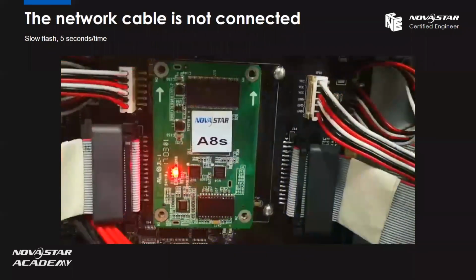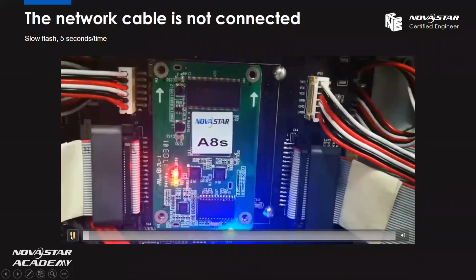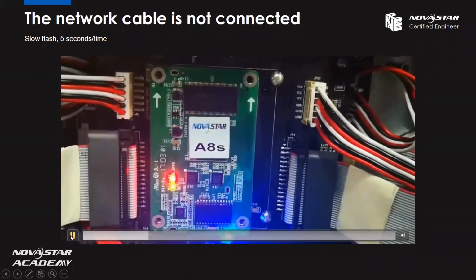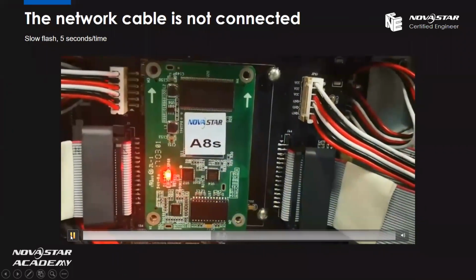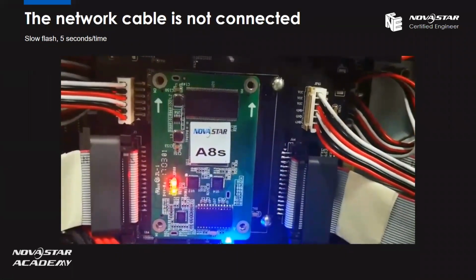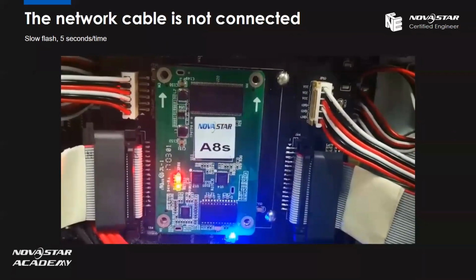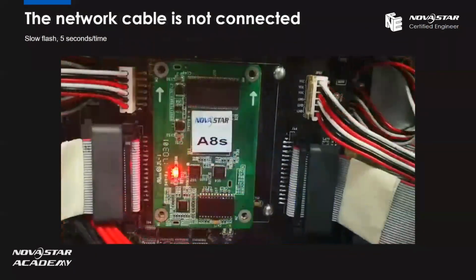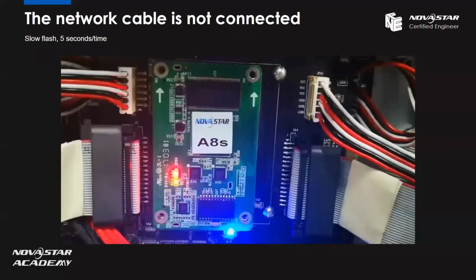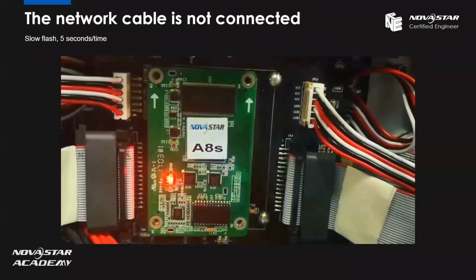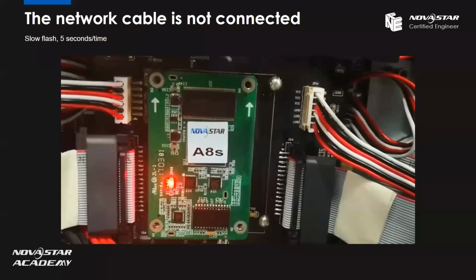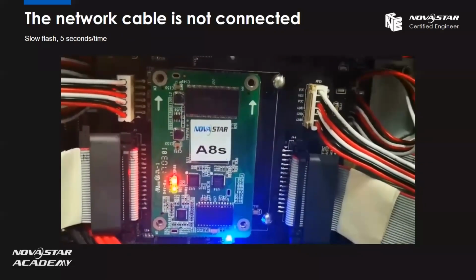Let's see the third situation, also a short video. Here we can see the receiving card green indicator light flashes very slowly, once every 5 seconds. So this situation means the network cable is not connected, and maybe we need to change to another network cable.